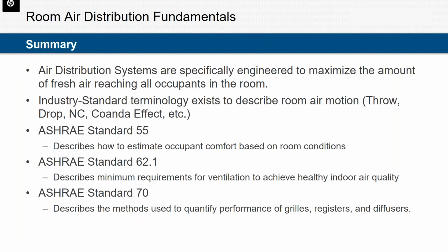So that concludes this presentation. For more information on all of these subjects, I would recommend you look at ASHRAE Standards 55, 62.1, and 70. There's also, within these standards, as well as the ASHRAE handbook, more terminology to describe air motion. And I hope this presentation has been informative to give you the foundations to move forward with your designs.